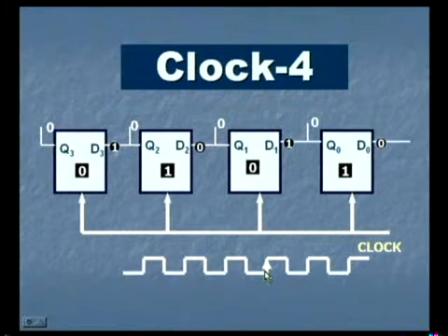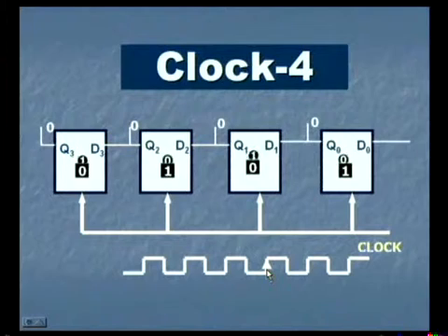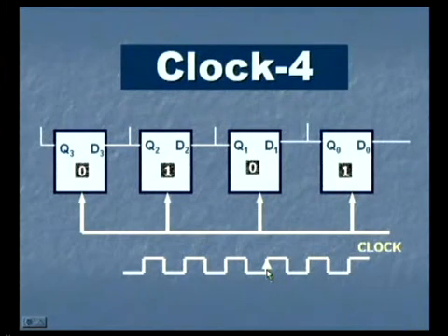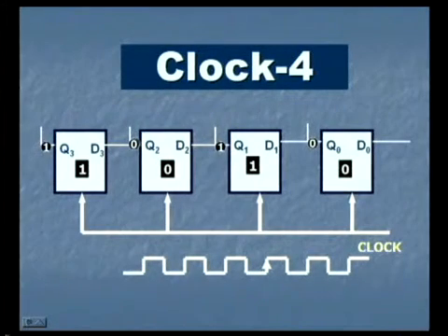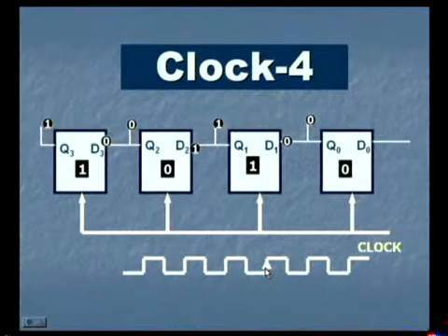On the fourth clock pulse, another bit is available at the input, and the previous bits have moved as input bits to the next flip-flops. What happens on the fourth clock pulse? These bits will be stored in the flip-flops and hence their content changes along with their outputs. So, the output available upon completion of the fourth clock pulse is 1 0 1 0.